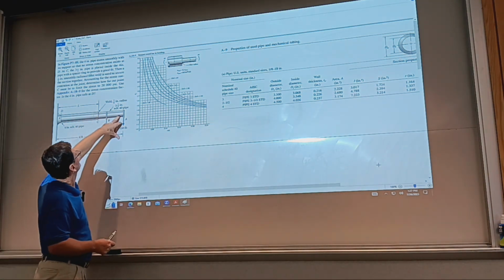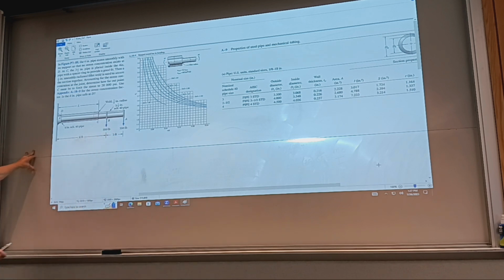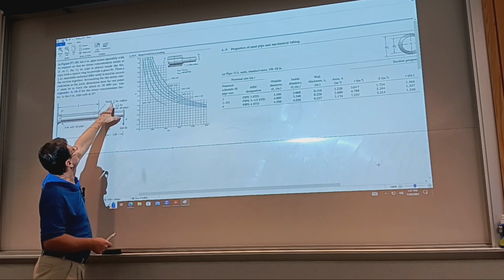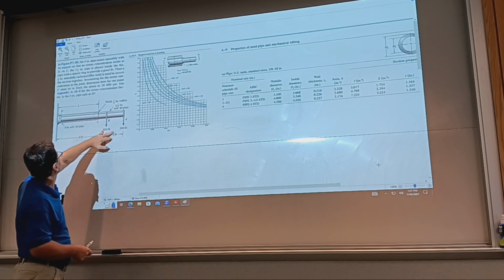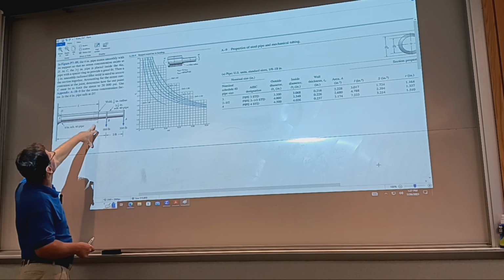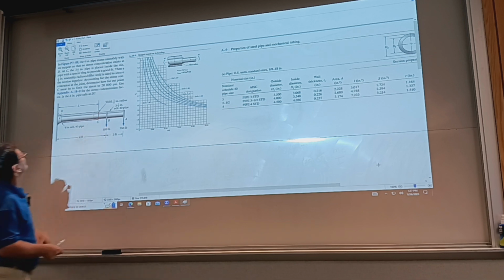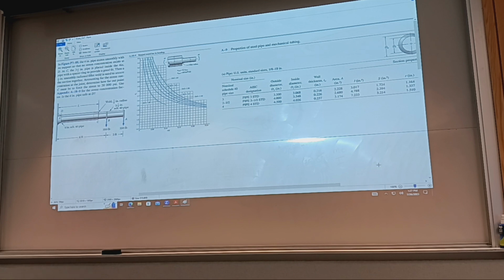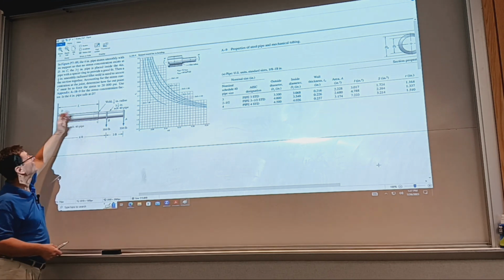And it's assembled with a 3.5-inch pipe. And there's a weldment, and it says the radius 1/4 inch. It's loaded as shown. And we want to limit, this is a stress concentrator. We want to limit the stress at location C to 20,000 PSI. What is the maximum L that we can go with?